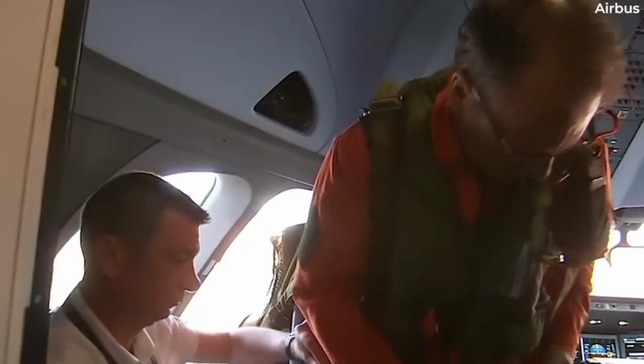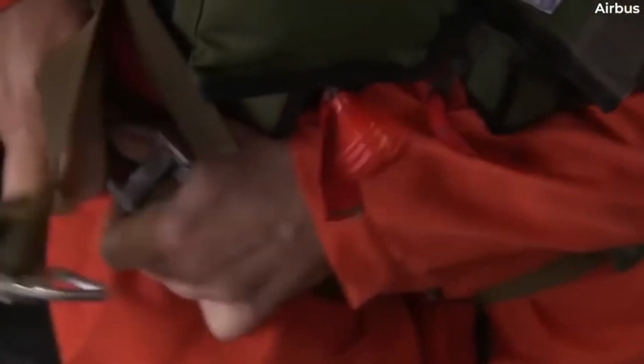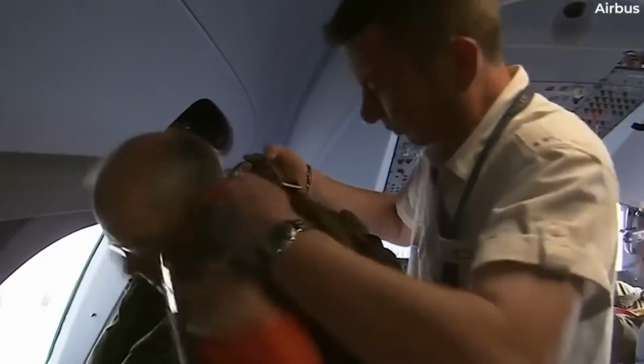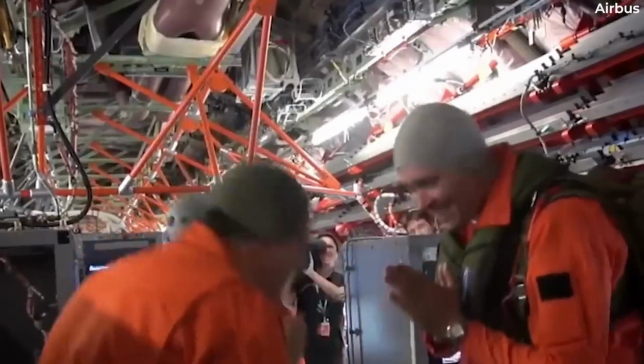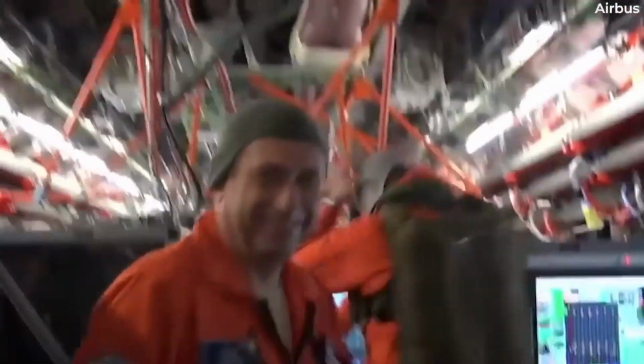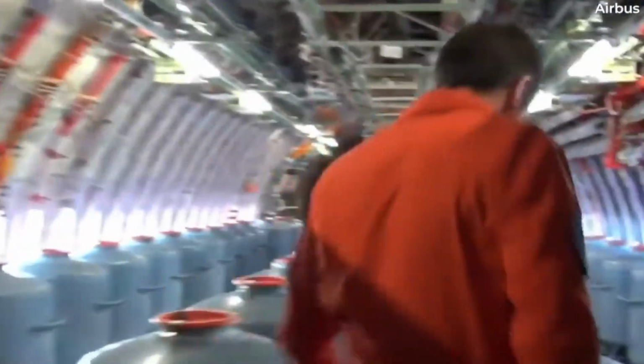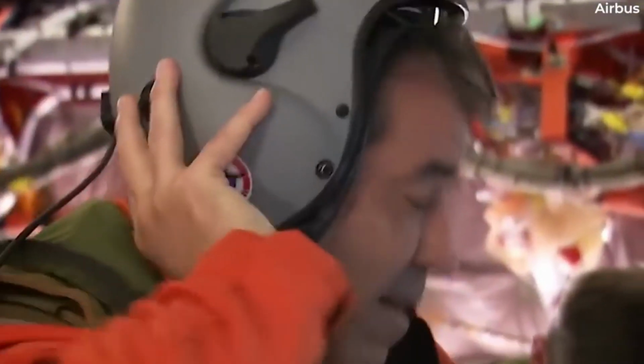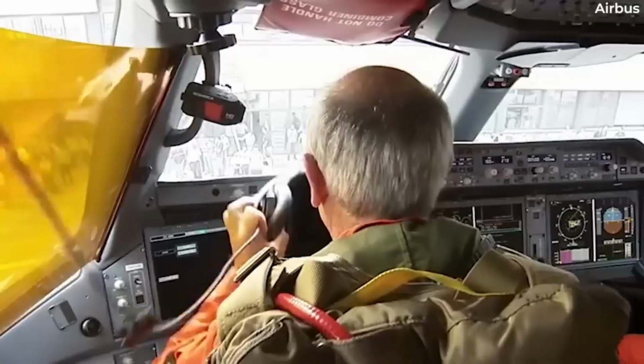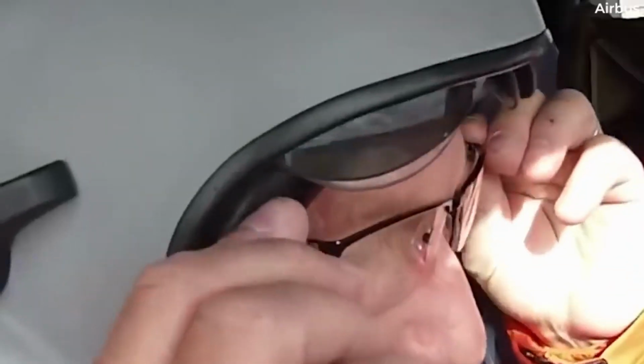The determination of whether the aircraft is large or small is based upon the definition provided in 14 CFR Part 1. If the aircraft has a maximum certificated takeoff weight of 12,500 pounds or more, it is a large aircraft. All aircraft less than 12,500 pounds maximum certificated takeoff weight are considered to be small aircraft.